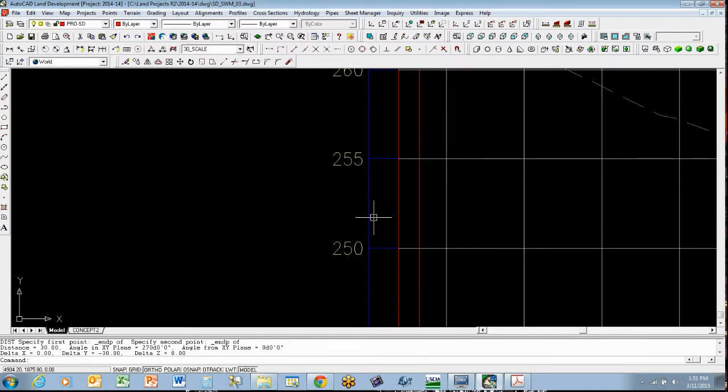So what that tells us is that for every 1 foot of vertical profile depth, it actually is 6 offset units. So if I were to offset this from 50 by 6, that would be 51, 52, 53, 54, and then finally 55.